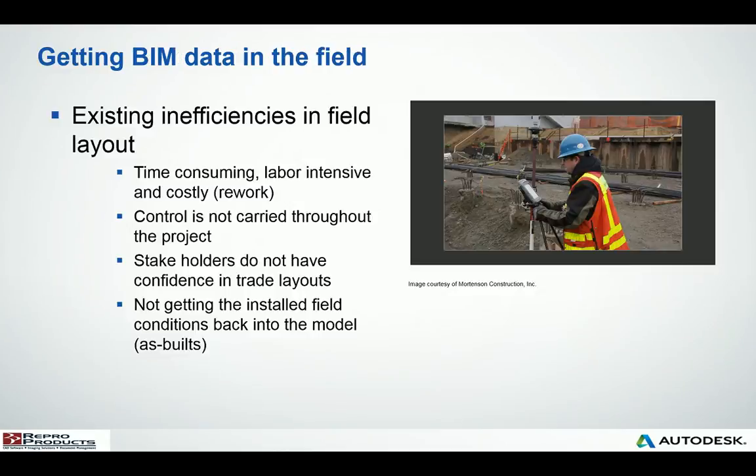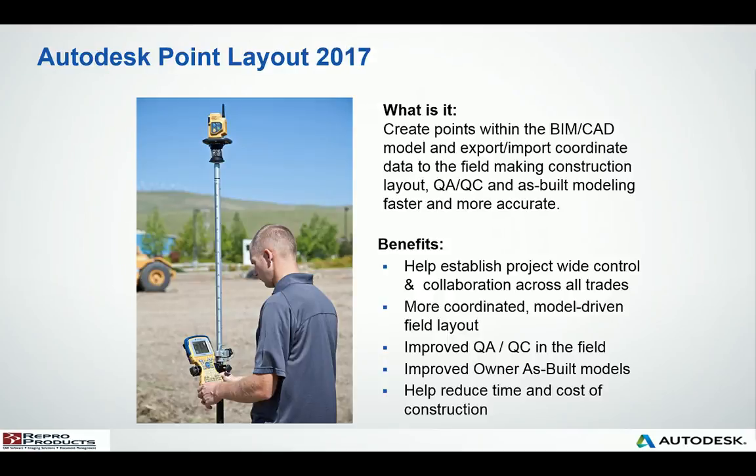So when we try to understand what Autodesk Point Layout is, it's a great tool to help us with understanding the different conditions that we have in the field that may be inefficient for marking and placing either existing or new conditions. We can use the software to generate the points that we need in the field for marking as-built conditions. We can take those points and then bring them into the digital 3D environment using, say, Navisworks or AutoCAD or Revit. And then from there, align that with our new design, or we can go the other way around.